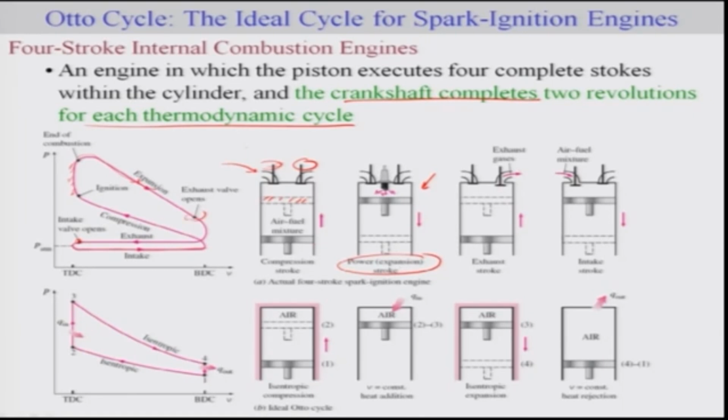Once your exhaust valve is open, this would be your exhaust stroke, so essentially the volume gets reduced, and then your air-fuel mixture is again replaced here. So you pass the air-fuel mixture which will expand the volume, which will be the intake stroke. This is your intake valve open, so this becomes your intake stroke. Though we are starting with the compression stroke, we can also start this analysis from the intake stroke. So let me go through this explanation again.